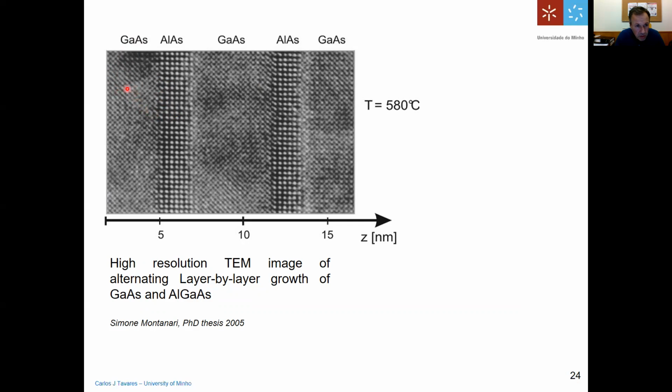Okay, so it means that the orientation of the crystals is different in both layers, and the lattice parameter is also different. But even if the materials are not isostructural, which means that they do not share the same lattice constants, you see that there is a very, very sharp interface between both materials. Okay, they grow. You can see some errors of the position there. If you look closely, sometimes you see that there are some faults in the structuring of the atoms, but these defects are very small. You have to pay really close attention to this micrograph to look at them.